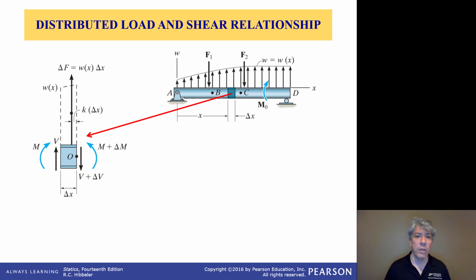Now, you can argue that there are compressive and tensile loads within the beam that make up the moment, but that's a topic for another class. For right now, we can think of it as shear on either face of this free body and moments on either face of this free body. Now, we're not claiming that the shear and the moment on both faces are exactly equal.